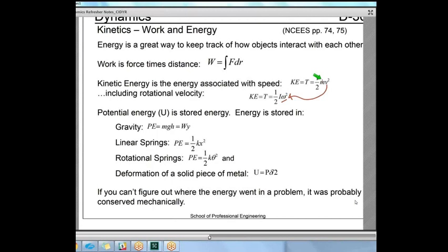All right, well, what does mass tell you about an object? Essentially, mass tells you how difficult it is to move something in a straight line. Due to F equals ma, specifically, the mass tells you what force you need to apply to accelerate something. In rotational terms, we need mass moment of inertia to tell us how difficult it is to rotate something. So as we go about translating equations from linear to rotational, anytime you see an m, it's going to turn into an I.